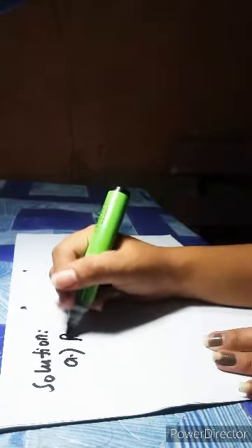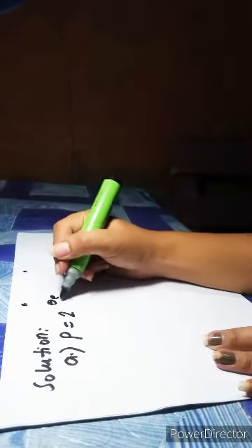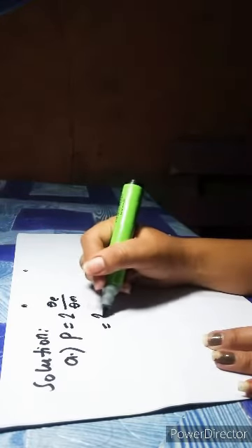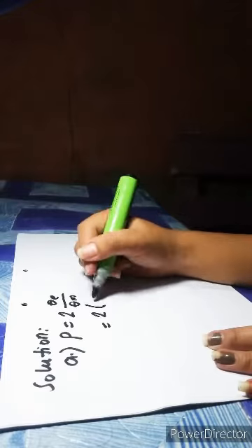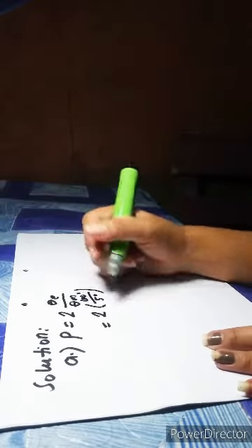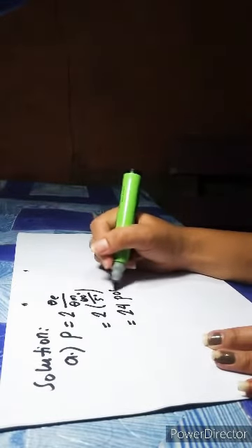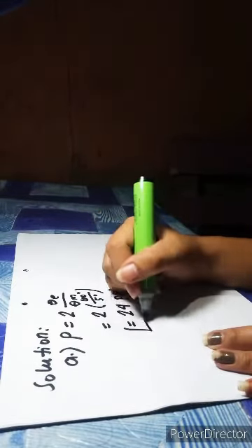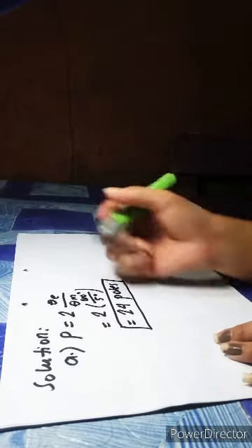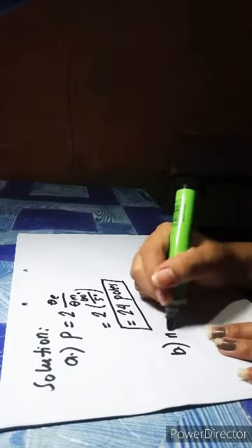We can find the number of poles. It is equal to 2 times the electrical angle over the mechanical angle, or 2 times 60 degrees over 5 degrees, which is equal to 24 poles. And B is to find the pulse rate received in the motor's control unit if it is to be driven at 250 revolutions per minute.